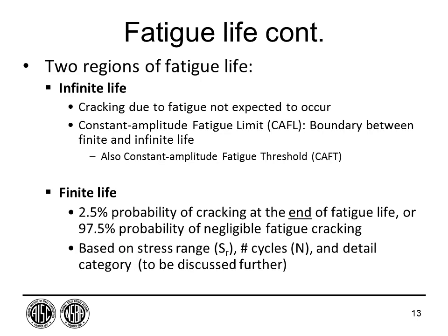Now we'll get some plots of curves here in a little bit that will help clarify some of this. But when we talk about fatigue, there are two regions of fatigue life that we need to worry about. The first one is the easiest one, and this is the infinite life region of a detail. Basically this says that it's not likely at all that fatigue cracking would occur at that stress range.